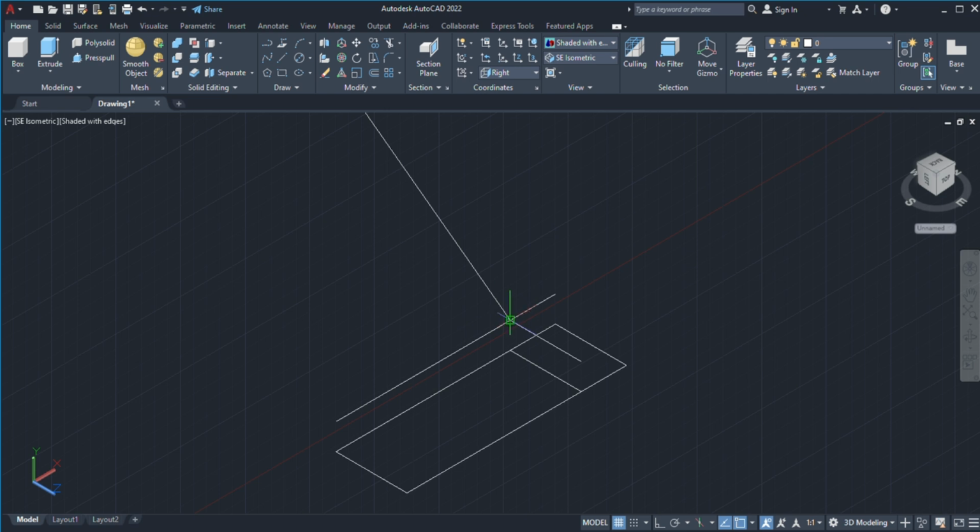We have been given another line of 60 millimeters going upwards at 90 degrees. So we draw a line of 60, type 60, then you tab and 90, enter, and again. Now we have the center point for the three circles of diameter 10, 20 and 25 respectively.